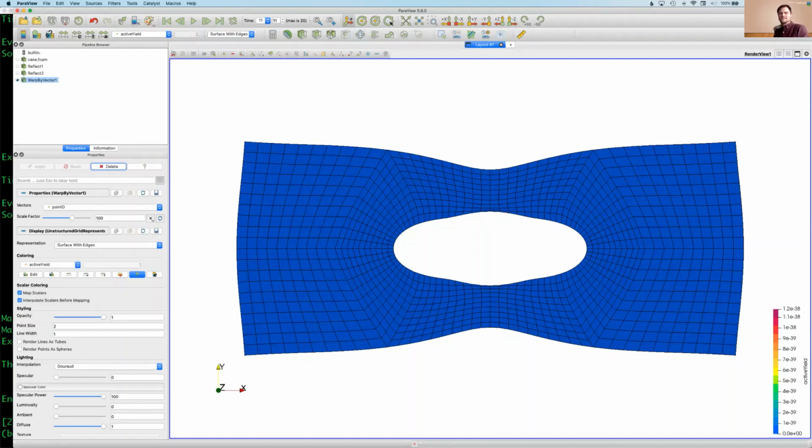However, it would still be an implicit solution algorithm, so it may not be the most efficient way because each time step might be expensive to solve. Even though for a segregated solution algorithm or an iterative one, it may actually not be that expensive. So what about actual explicit methods? In finite element analysis, for crash or blast problems, you really use explicit finite element procedures.